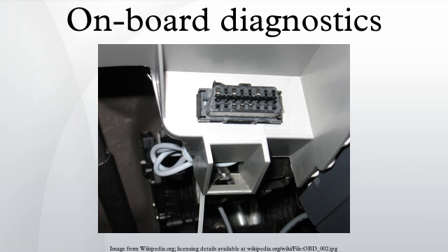Among others, the following information is available: VIN, vehicle ID, CALID, ID for the software installed on the ECU, CVN, a number used to verify the integrity of the vehicle software. The manufacturer is responsible for determining the method of calculating CVN, for example using checksum.